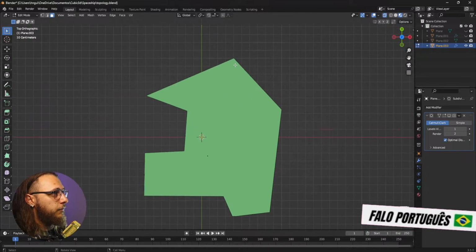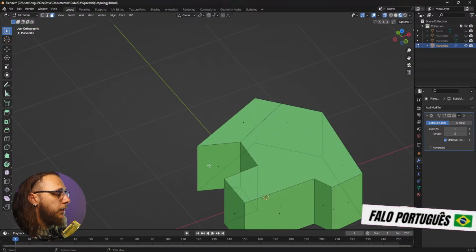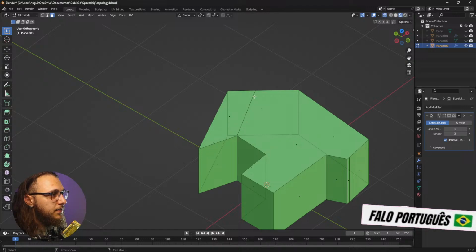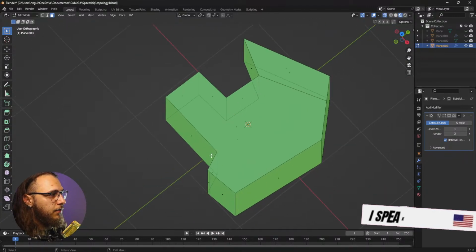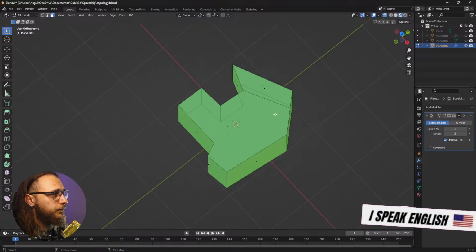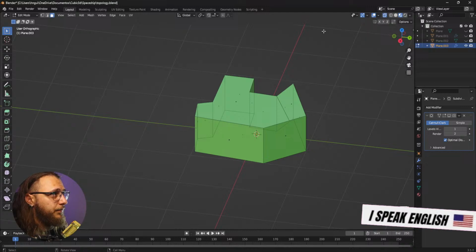So we want to follow what edges are present in the model. So we can pick a knife and cut it here. When we cut it here, we create a face and we create a quad. This is a pretty big deal because we are trying to eliminate the big n-gon here, and creating quads is a good way to do that.